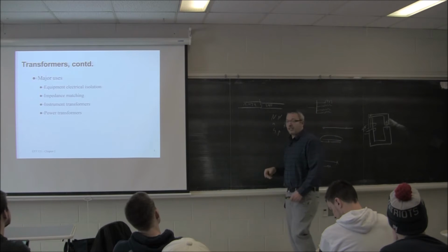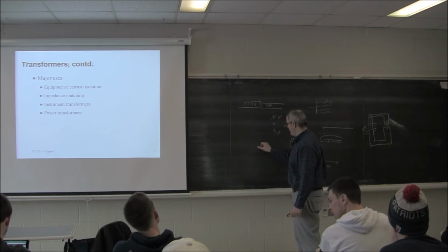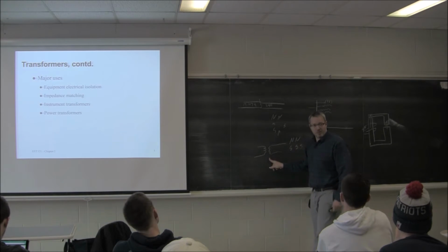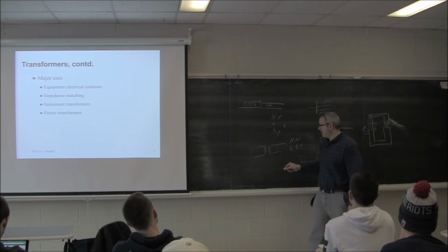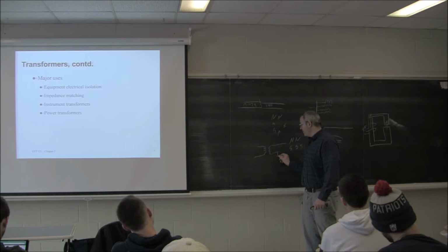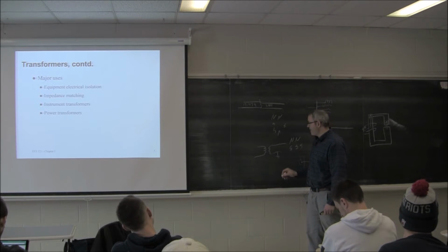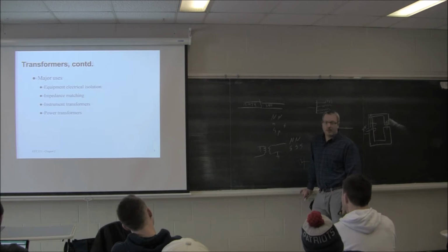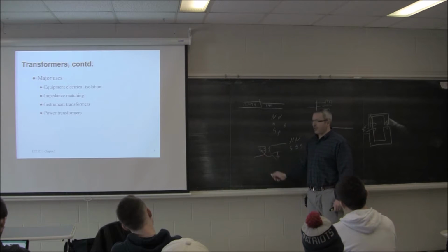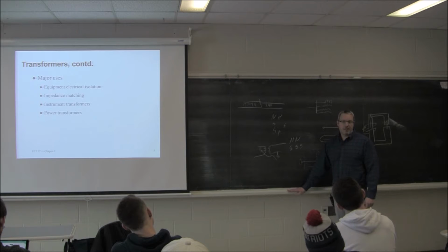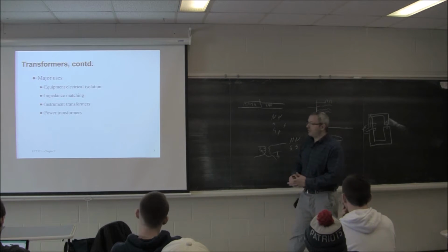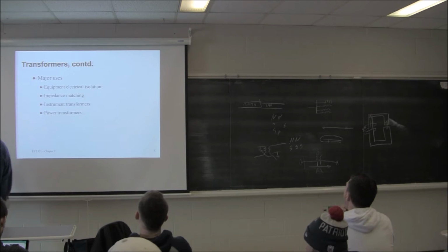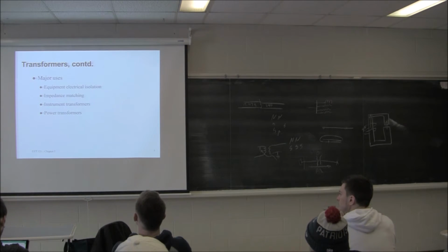So having that electrical isolation, if I actually have a transformer, and these two, there's no electrical connection between the two, right? This is all magnetic energy. If I have a ground over here, and a ground over here, what happens? Nothing. There's no path for the electrons to flow through and continue on that path. So having this electrical isolation is really a big benefit because nobody would want to connect their house if they had the possibility of being energized at that value.